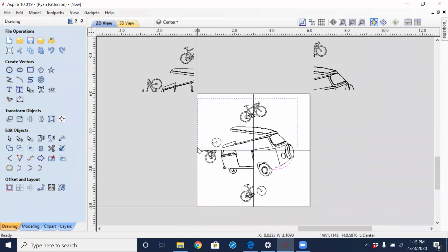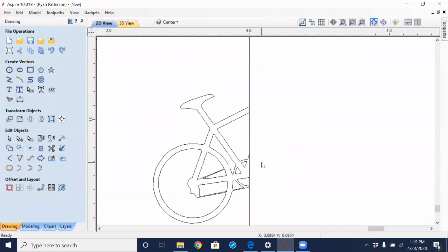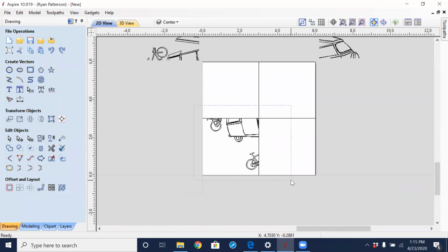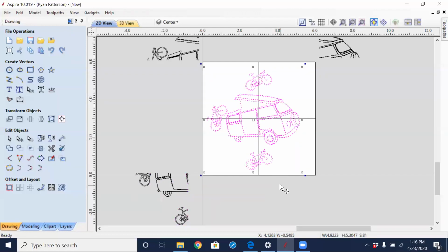Doing a sweep select to select everything, holding the control or the shift down to deselect that line. And I can just delete the objects that I do not want simply by hitting delete on the keyboard. And just remove that one as well. I'm going to group that together, letter G, and move that off to the bottom left. One more final one, a Control V, which is pasting back my original item there that I did way back in the beginning.